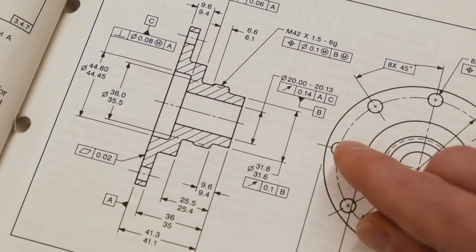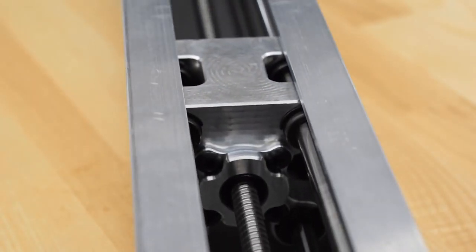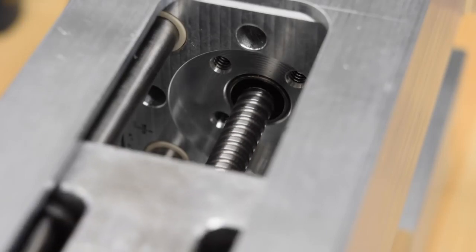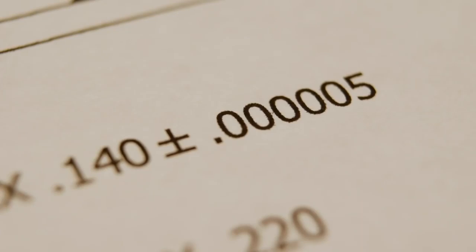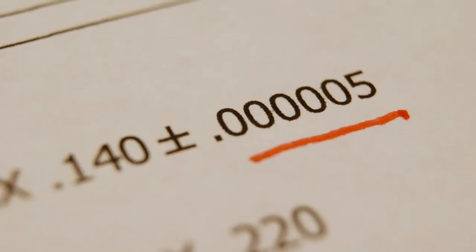If it sounds complicated now, don't worry, because we're going to break it all down into much simpler terms in future videos. The important thing we want to emphasize is that there is a systematic way to calculate what every single tolerance should be to achieve the intended functionality. It's terrible practice to put an arbitrarily tight tolerance on a dimension just because you think it's a critical feature.